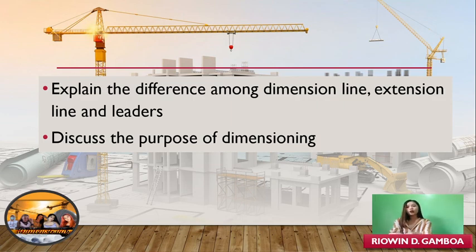And what is the purpose of dimensioning? The purpose of dimensioning is to provide a clear and complete description of an object. A complete set of dimensions will permit only one interpretation needed to construct the part. And dimensioning should follow the guidelines like accuracy, clearness, completeness, and readability.